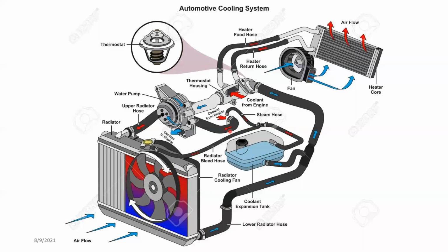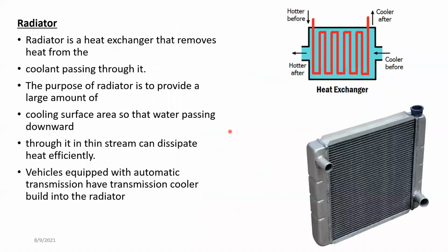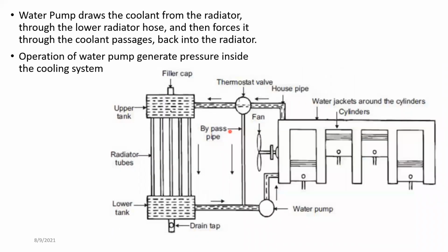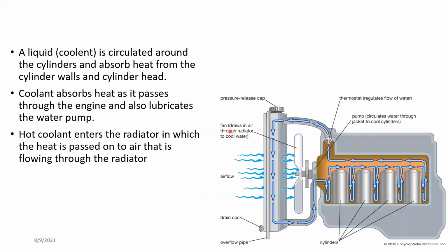So one more thing, if we go back. If you look here, one thing we always have to remember is that the radiator pressure release cap, in this case, has to be on the highest location of the engine.